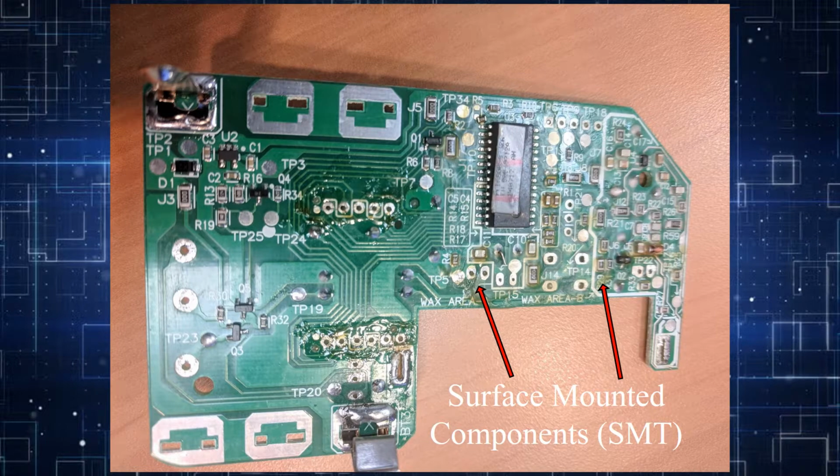The surface-mounted components, on the other hand, are commonly attached to PCB boards by reflow soldering. If reflow soldering were used for the SMT components, however, then the wave soldering process would need to be applied last, so none of the through-hole components melt in the reflow oven. However, if the wave soldering were applied after the reflow soldering of the SMT components on the lead side of the board, then the SMT components would be soldered twice, which can cause defects, such as solder shorts.